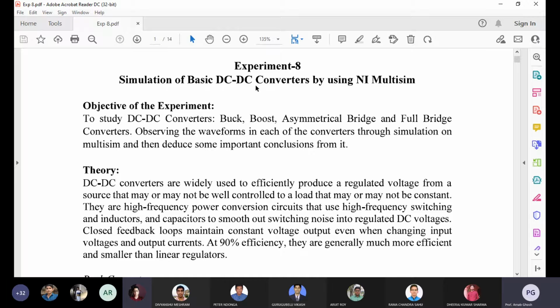These are all second order choppers, with only 2 energy storing elements. After that we can see some derived converters, which means cascading of DC-DC converters. Suppose we cascade a buck converter and a boost converter. Then we can observe that the number of energy storing elements also increases.